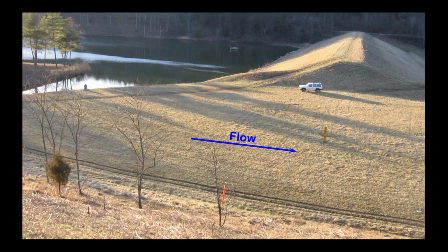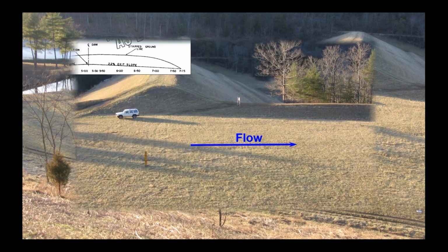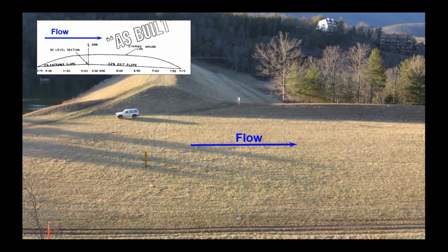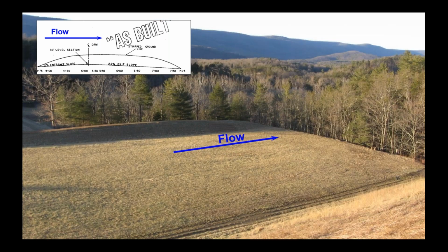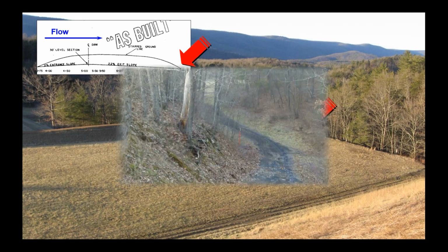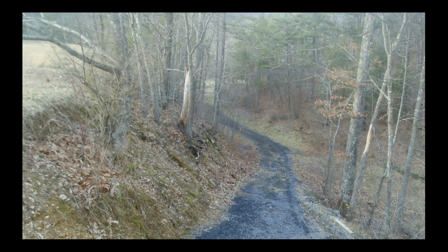Now this spillway looks pretty good. It has a good grass cover. It still has the problem with these tire tracks. I imagine if that was to initiate, that's where it would erode first. But this spillway has a different problem. As you go down to the downstream end of the spillway, where it transitions into the valley bottom, let's see what's going on there. In this case, it looks like the farmer excavated an access road. So what's going to happen here is the flow that's going over the 2% grade all of a sudden now drops almost vertically, and there's no transition anymore to the valley bottom.